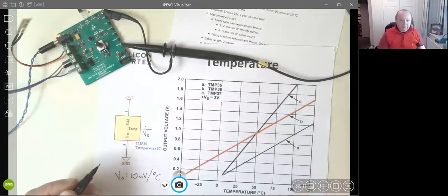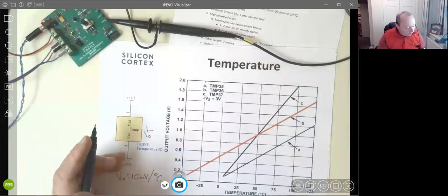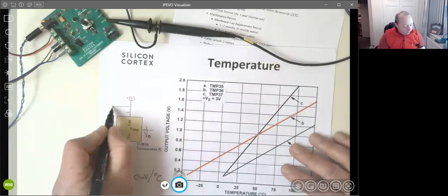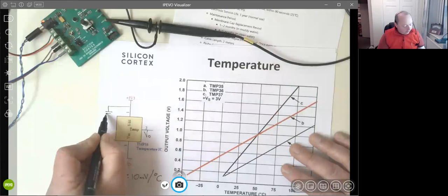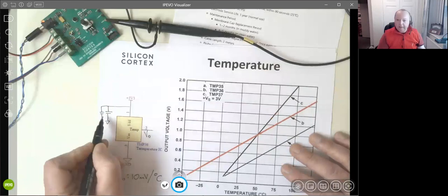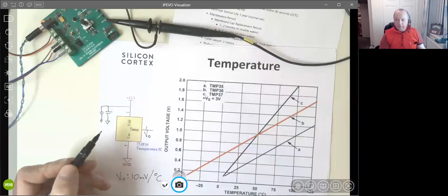Yes, exactly. So I'm going to draw on this circuit here what I would do to answer John's question. Very close to the pins of the power supply, I always add some decoupling to keep noise out, because you don't want noise to affect the quality of the signal.